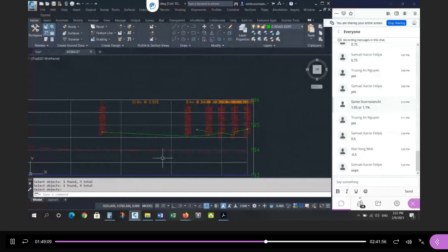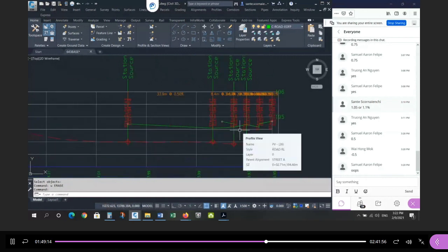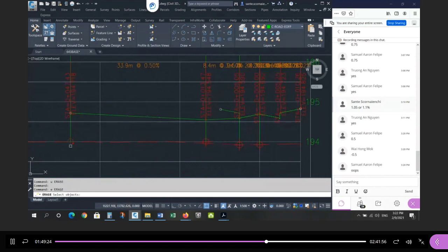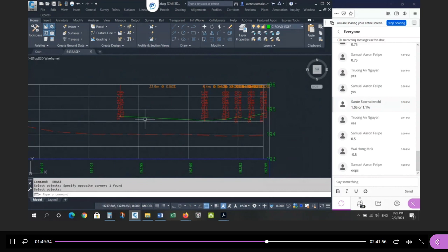That's my design, right? But why are those points at those station locations? Because of these key locations in plan. The station locations in the profile come from key locations in the plan. And that's why we project the points from plan to profile. Once you trace them, right, you've established the stations in your design, you no longer need the reference points. So you can delete these, they're not going to change. And you can delete this, you're matching. Okay, so there's the design. So I'm going to stop there.